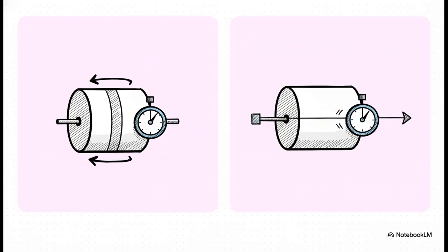When you're looking at these tolerances, you really have to consider the manufacturing realities. Things like turning or grinding operations can very easily introduce 2D or 3D variations. Tool wear, machine vibration, or even material distortion. Those are exactly the things causing the variation you eventually see popping up on that dial indicator.